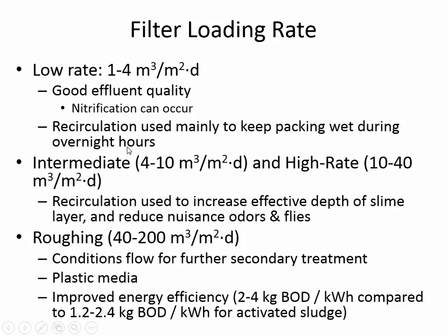During the overnight hours, recirculation has to either be used or you have to have a flow equalization basin to try and even out the peaks of high flow rates during the day and low flow rates at night. And so in a low rate filter, you've got a really big area, a very, very big diameter. And they have to do recirculation there at night just to simply keep the filter packing wet.